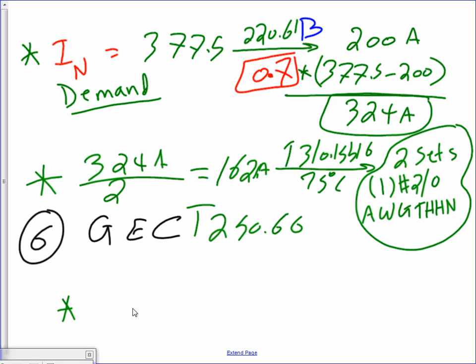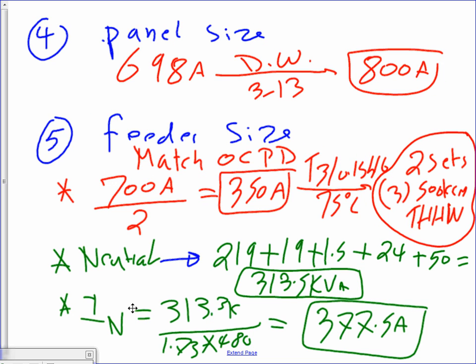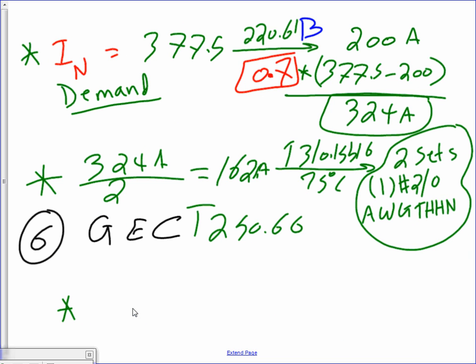Okay, now we size the neutral. We have two sets of neutral. We bring a conduit, guys, put 4 conductors in it. What was the size of the phases? The size of the phases were 500. So 3 conductors, 500, and 1 conductor, number 2. Grounding electrode conductor and main bonding jumper, and then we're done, gentlemen.